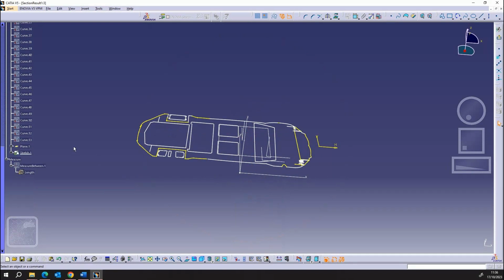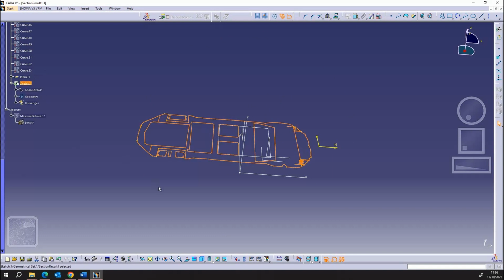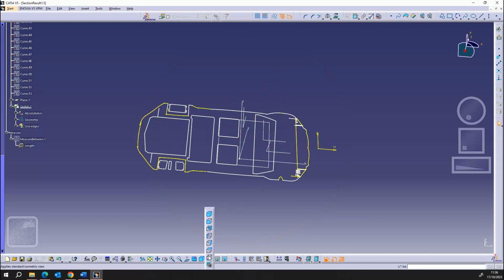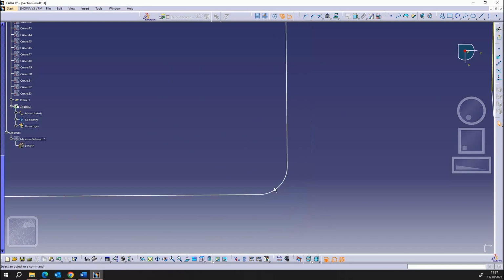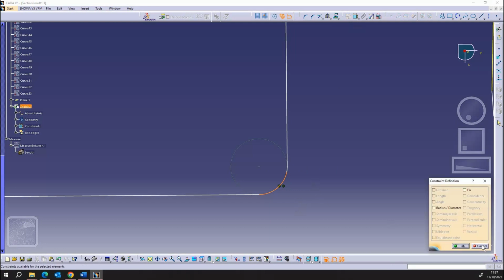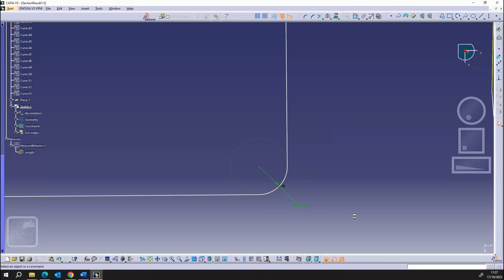the radius. So now we've hidden everything, and we can come to our sketch. Now when in sketch we can select the top plane. To do that we can use a 3-point arc, measure from one point to the next. And because the arc is coincident to this other arc, we can see that the radius is 30.053. So that's a simple way to measure your arcs as well.